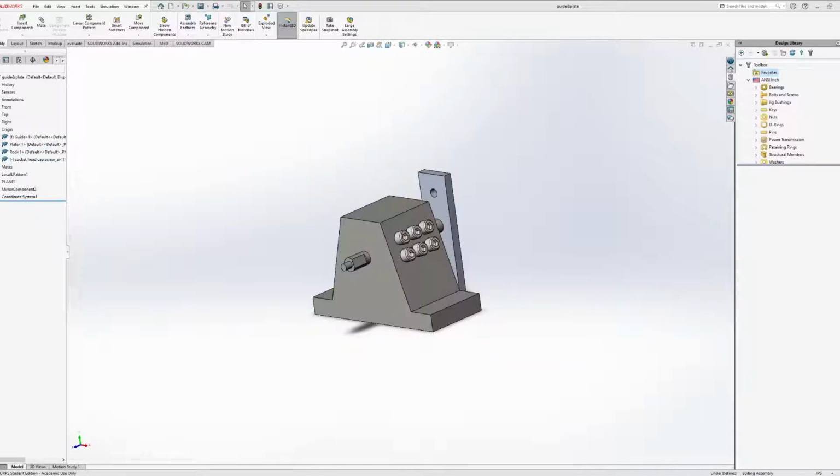And just so it's on record for the recording, since I stopped recording for a moment, the order of operations for creating your assembly, parts, and zip file is to use Pack and Go as a folder as opposed to a zip file. Save the assembly into the folder that you use Pack and Go for.